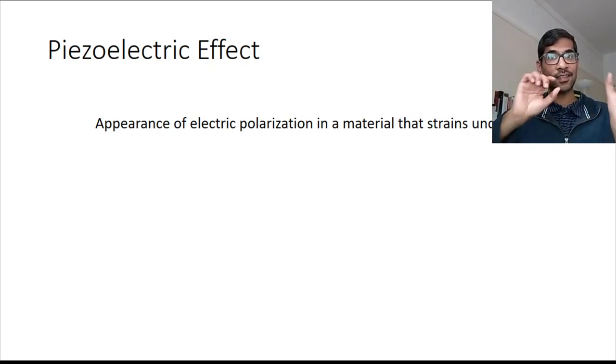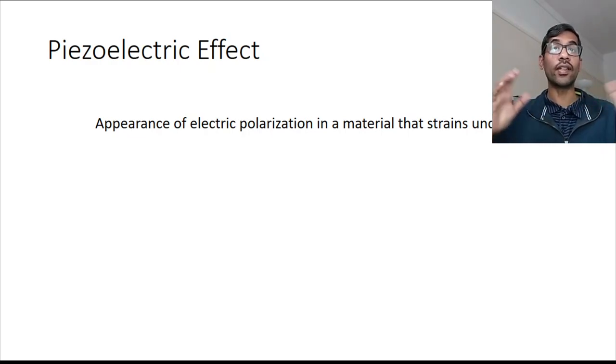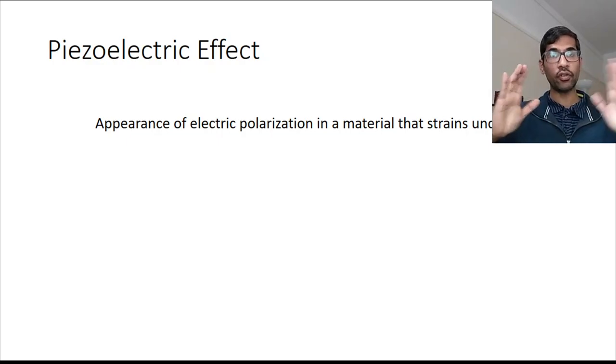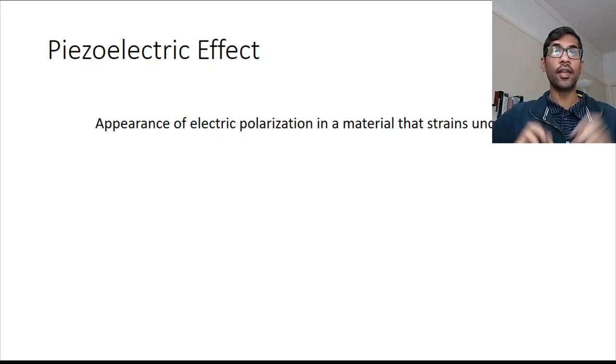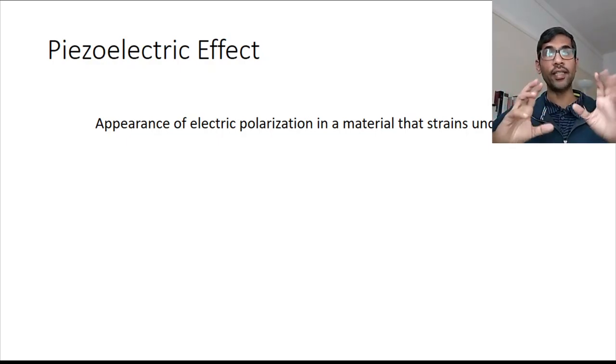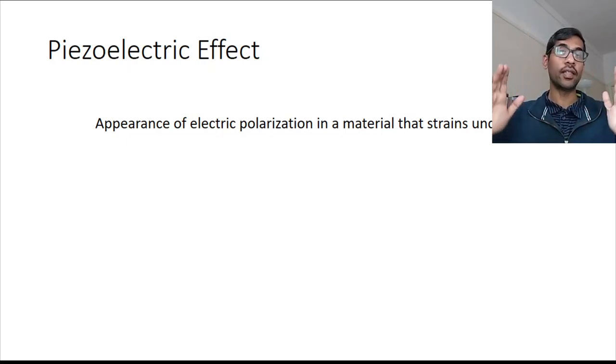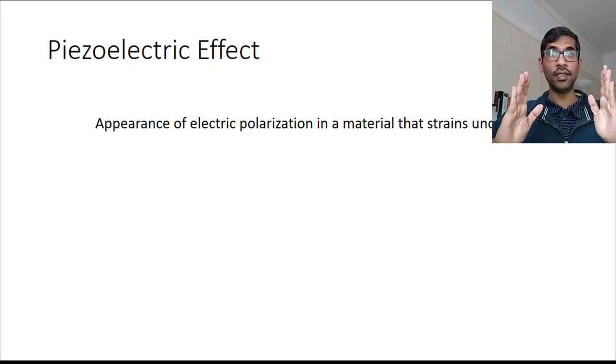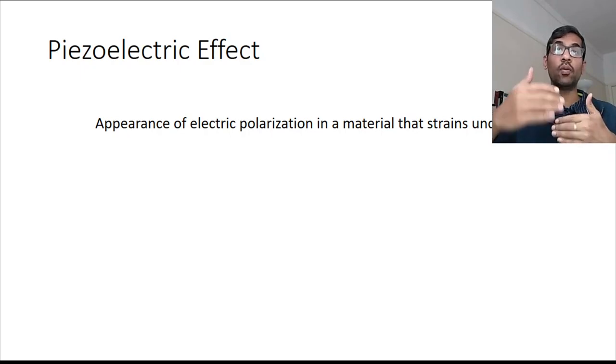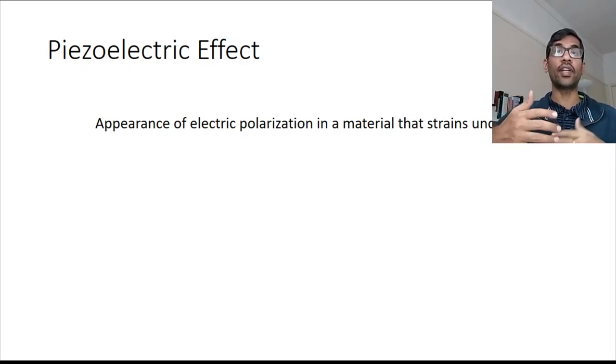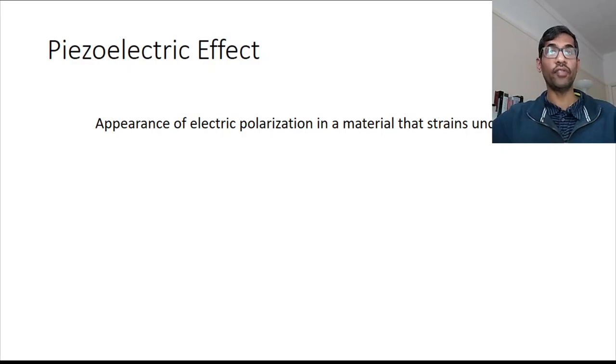So this expansion or compression is called strain. When you apply a stress, you have a strain on the material. And when you have a strain in piezoelectric material, in addition to having a strain, you also have a voltage or a charge develop across two faces of the solid.